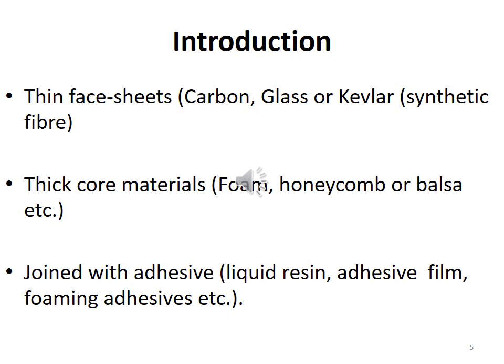The two layers are thin face sheets, which are made up of carbon, glass, or Kevlar, a synthetic fiber, and between these two face sheets is a thick core material, which is made up of foam, honeycomb, and these three components are joined together by using some adhesive material such as liquid resin, adhesive film, or foaming adhesive.